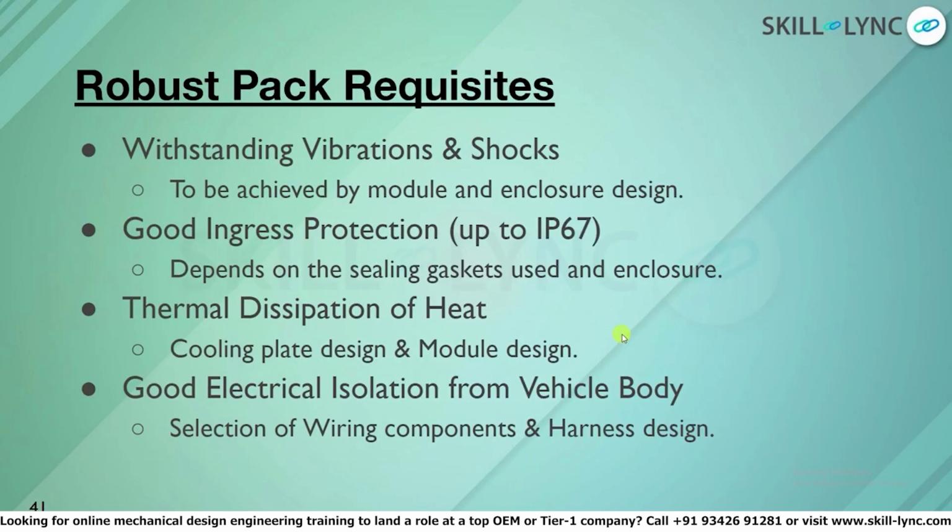Now a robust battery pack should have certain qualities where it should be able to withstand vibrations and shocks. That means it's not just the pack; the module, when it is designed, should also sustain such kind of vibration. Usually in India we follow AIS standards, which call for at least 3G load vibration.